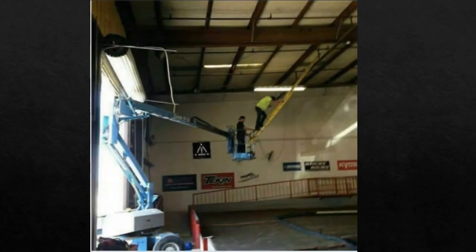I talked before about how you should never use step ladders or extension ladders on scaffolding. Well, these JLG and other lifts are essentially mobile scaffolding, and as you can guess, that ladder is not anchored very well at all. Plus, when you get somebody on a ladder that's connected to one of these lift buckets, that's an awful lot of strain being placed on the lift bucket itself and on the outriggers that you might or might not have down there, or the counterweights that are keeping that lift bucket upright. So this is a recipe for an overturned bucket, for the ladder slipping, and for something really devastating happening.